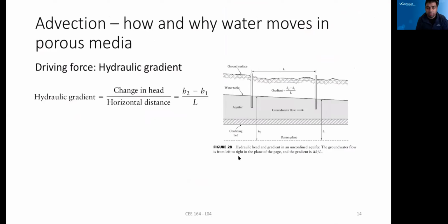So for different sites, you have to also compare how far it can migrate. What controls is the hydraulic gradient. Hydraulic gradient means, think of this way: if you pick a glass of water at a different height, and you connect them with a pipe, it always moves from the higher to lower. So that's the hydraulic gradient. It means the heads are different. The water height at two different locations are different with respect to the surface of Earth. So that's the exact same concept.